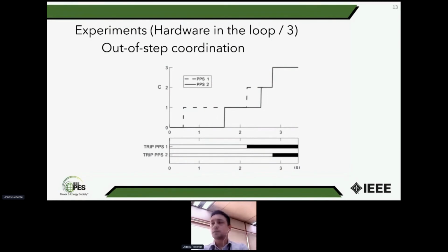In this slide, we had this special protection scheme actuating very fast, something less than 400 milliseconds, 200 milliseconds in most cases. And one of the protection schemes, a backup for the special protection scheme, actuates at about 2 seconds, and the second backup protection scheme at about 3 seconds. So we had a coordination for the worst case of about 500 milliseconds that we consider a good coordination for this type of phenomena.